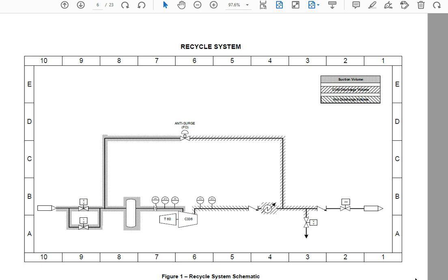In this video, I'm going to describe how to design an anti-surge system for a centrifugal compressor that protects against surging on fast stops. I'm not going to describe what a surge is on a centrifugal compressor. I'm not going to talk about controlling for surge avoidance in continuous operation. I'm just addressing the problem of a fast stop of the machine and equalizing the pressures around the compressor fast enough to avoid a compressor surge.